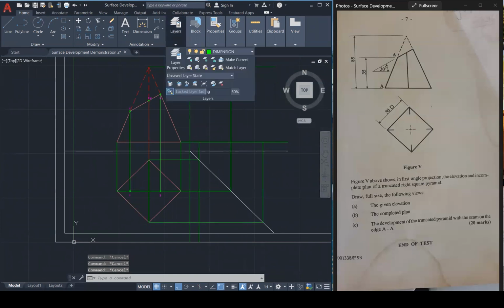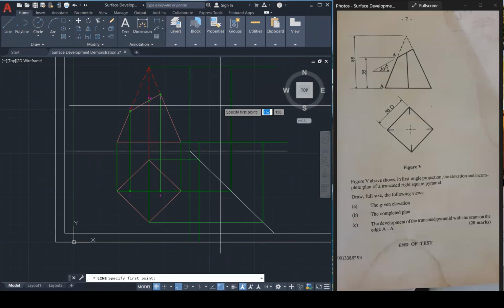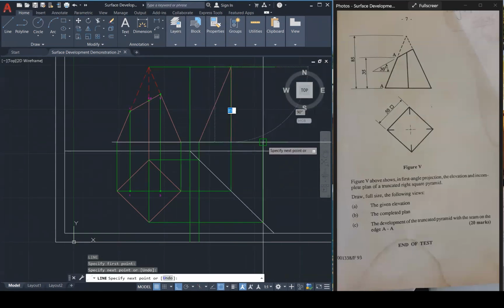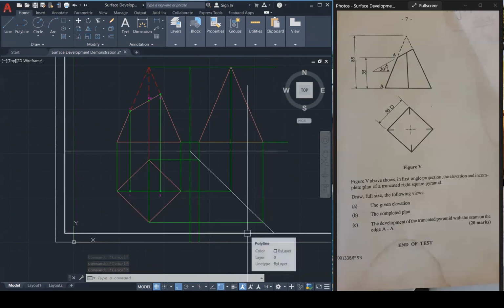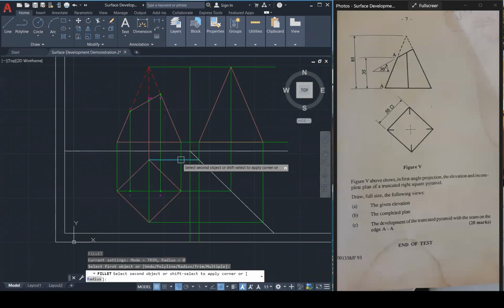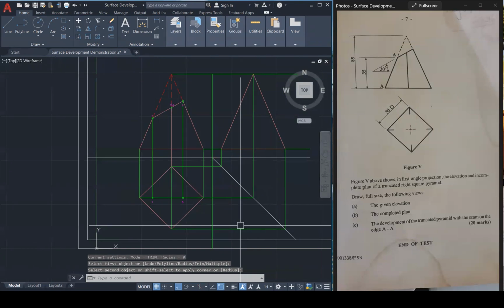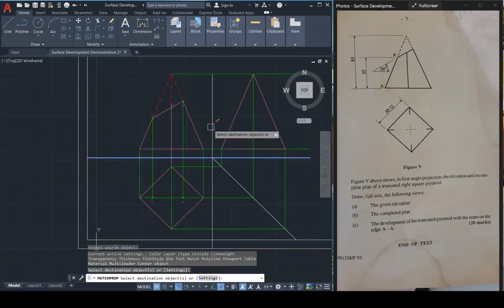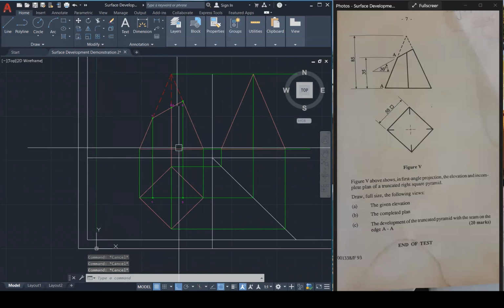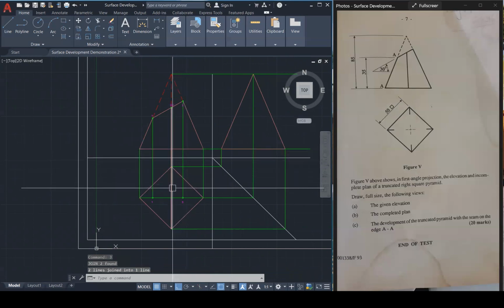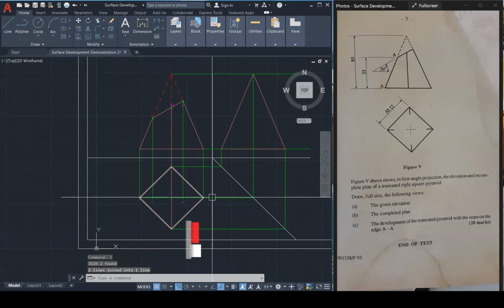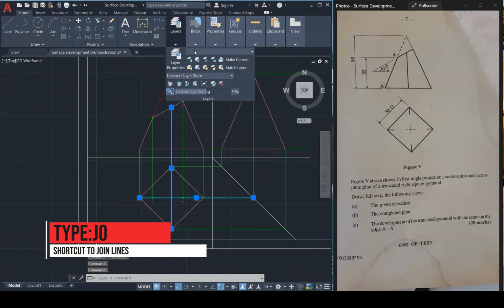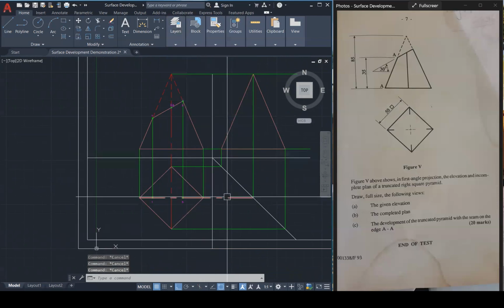And then from there, I'm going to go over to another there. I'm going to create the triangle over here. Cool. That triangle is established. Cool, cool, cool. And let's clean up this. I like cleaning it, so that I can see things clearly, right? But this line and that line, I'm going to join. This line and that line, I'm going to join as well. Reason being is I'm going to put these two lines into my center lines layer.